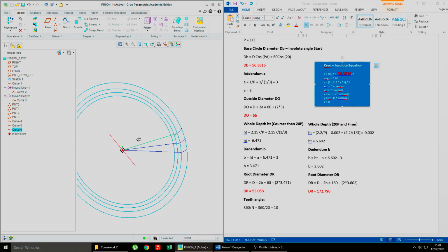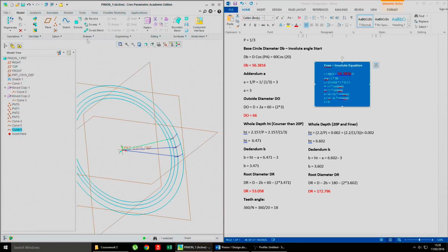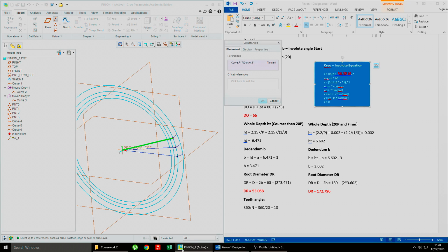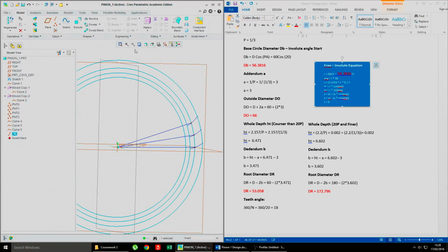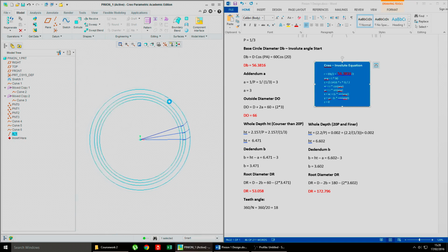So the next thing is you want to make an axis. So an axis along the z-axis. So there's your axis symbol. Oh, that didn't work. Yeah, datum axis. You're going to click your z-axis here. That's going to make an axis about the z-axis. This is going to be your rotational axis for this gear. Put it on front view, see what's going on.